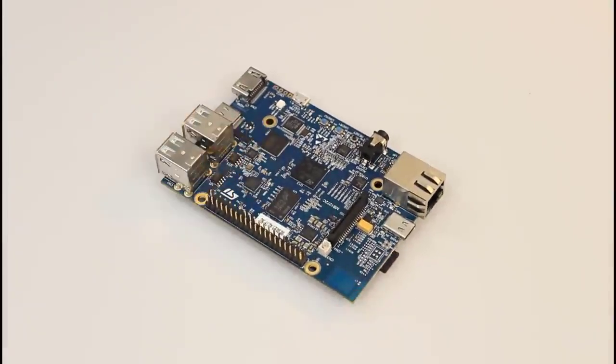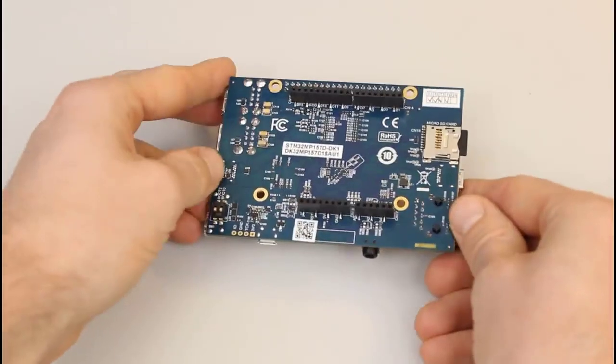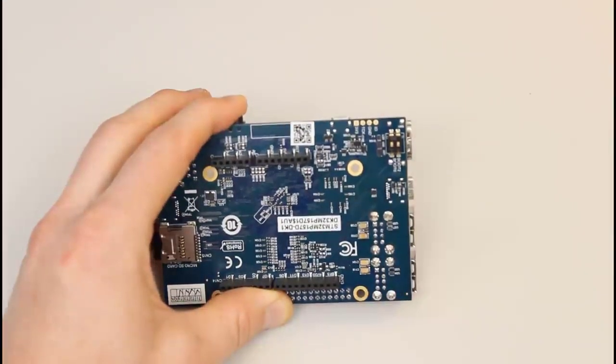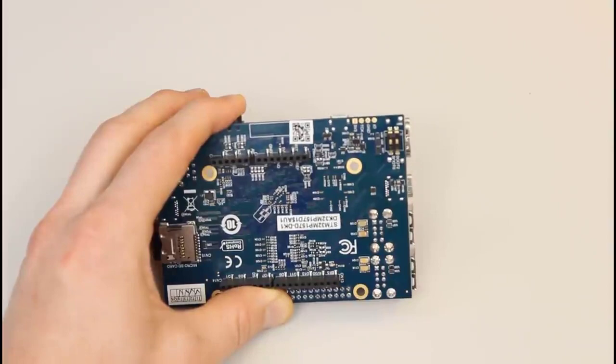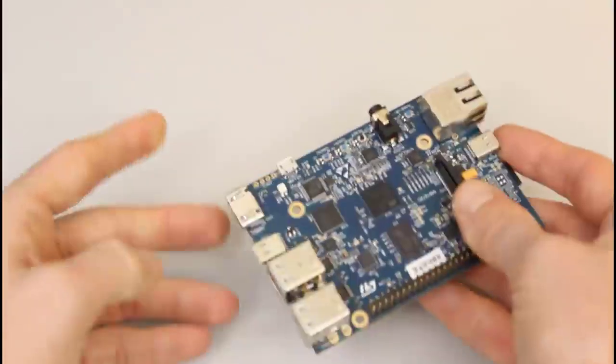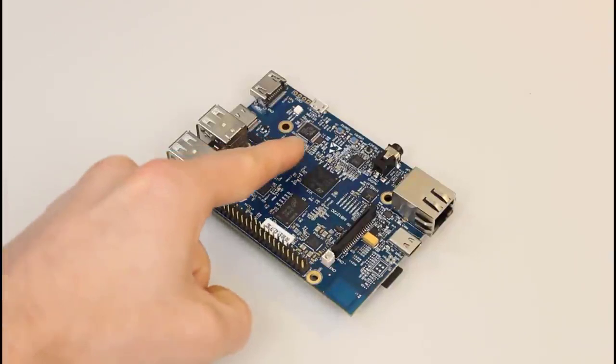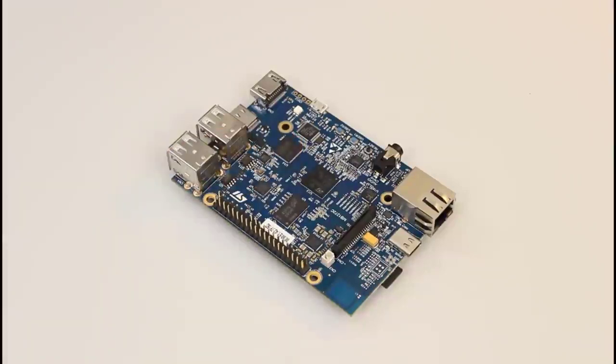For this particular board, you'll want to flip the boot 0 and boot 2 switches to on in order to have it boot from the SD card. Almost all embedded Linux boards will have a serial port dedicated to providing a console. On this particular board, UART4 is tied to the onboard ST-Link debugger, which also does USB to serial translation. By default, the configuration file has UART4 being used as the console port.